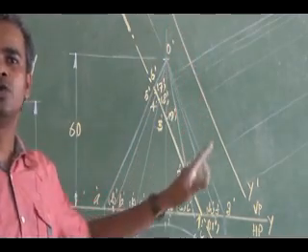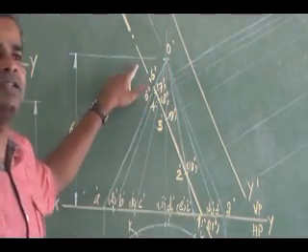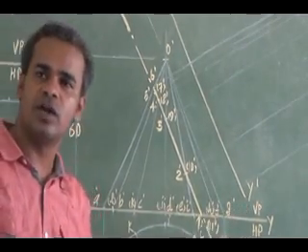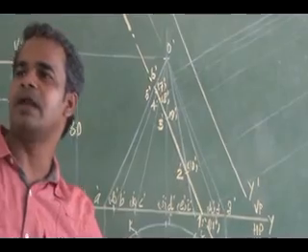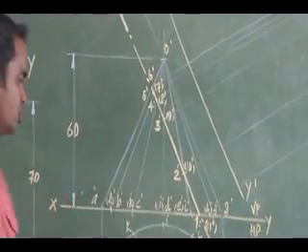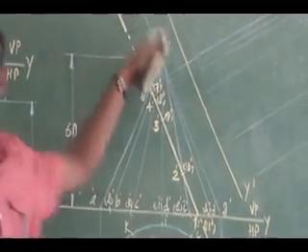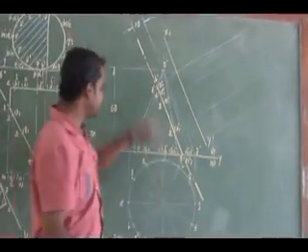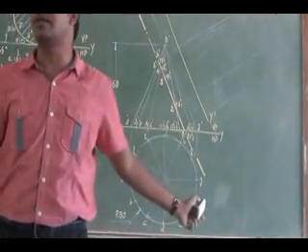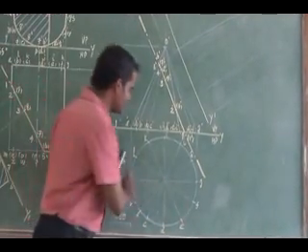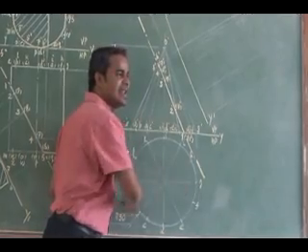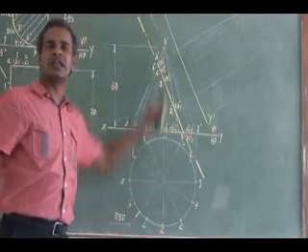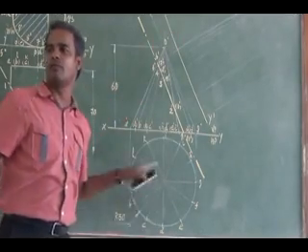So in an order you look for a hidden cutting point, then come back in the same manner looking for the visible cutting point, then come back in the same manner searching for the hidden cutting point. So totally I have 11 cutting points. These cutting points have to be marked in my top view, projected in my top view. So for the generator cutting points, this is something like a pyramid, so it is a cone. So these generators will be seen as lines in the top view. So carefully you get these cutting points, transfer these front view cutting points to the top view.